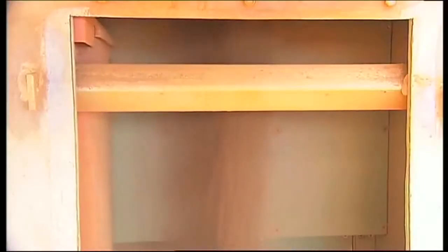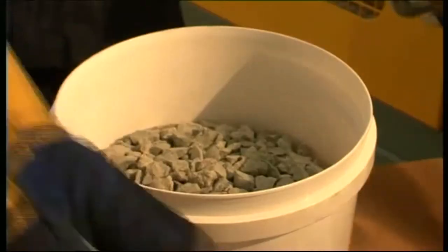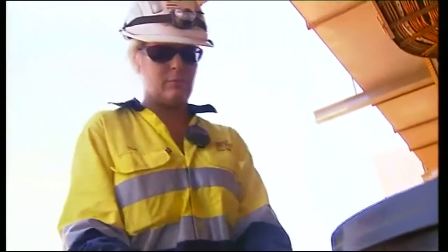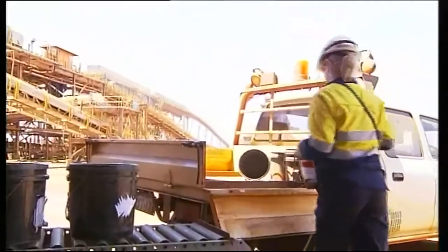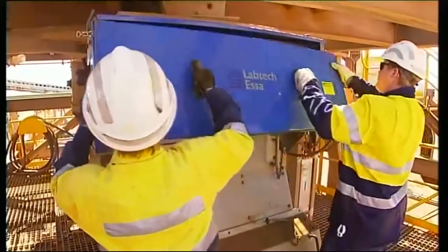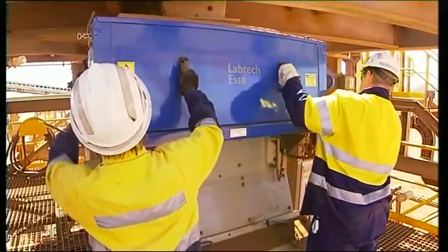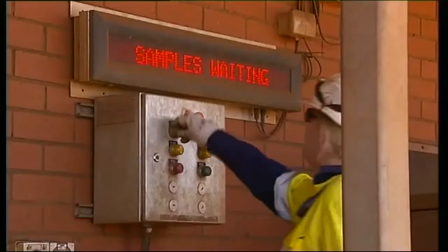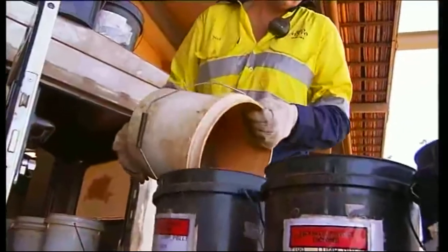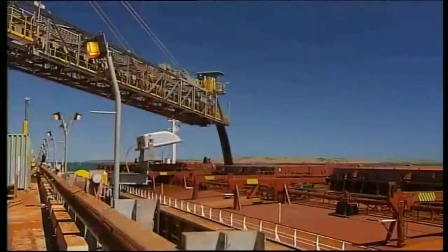samples. Good sampling practice is governed by the use of proven system designs and procedures, which comply with internationally accepted principles. The objective is to reduce the primary increment in an unbiased way to a size that is manageable for transport to the laboratory without compromising sample integrity. ESSA designed, manufactured and installed the equipment here to ensure that the final sample presented for laboratory preparation and analysis will be truly representative of the original material.